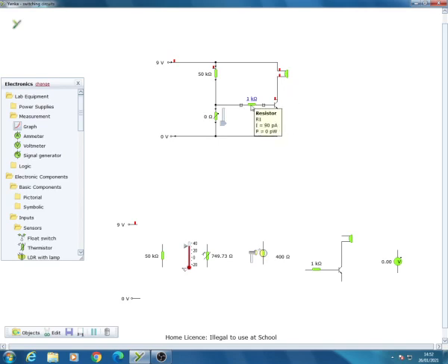There's one little extra thing that I put in this circuit this time, and that's a little protecting resistor here. This resistor here, just same as we do with an LED, it just stops too much current going into the transistor and blowing it up. So it's just there for a little bit of protection.